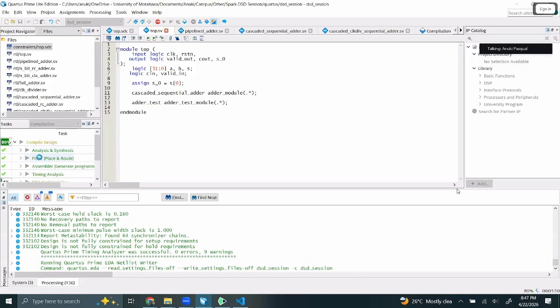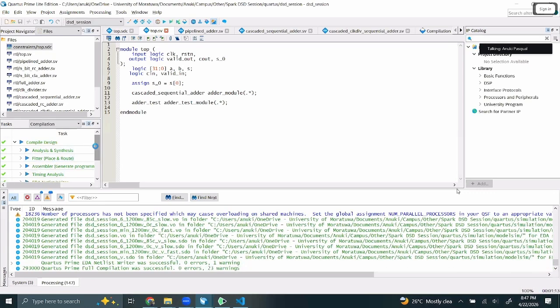So here it shows what the steps in compilation are. Timing analysis is one of the steps. Place and route is when you allocate each of the logic components that are used in the design to different parts of the FPGA. And after you do that, you connect all of them with the FPGA's pre-configurable wiring. And after those things are configured, it does timing analysis.